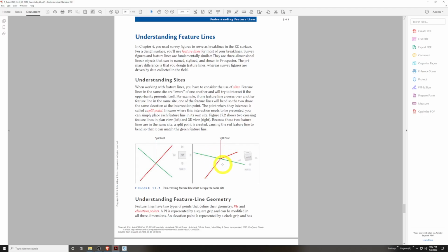That's a little deeper too, with types and styles of feature lines, and corridors have feature lines in them as well. These are more your feature lines outside of corridors that you can make on your own. There's a hierarchy of feature lines, and depending on the hierarchy in your Civil 3D styles, one will overtake the other. I can go into that just briefly in a moment.